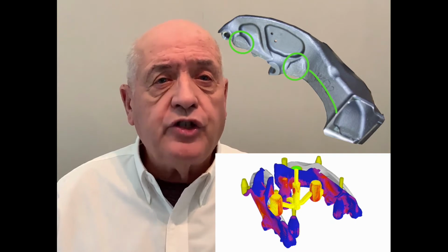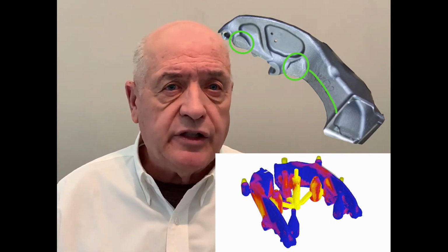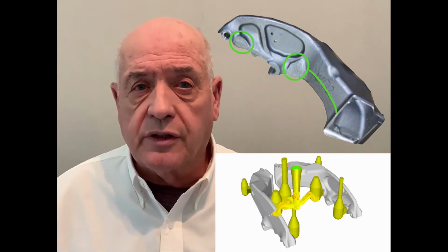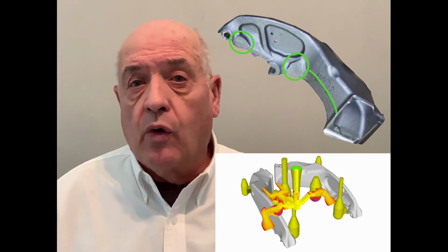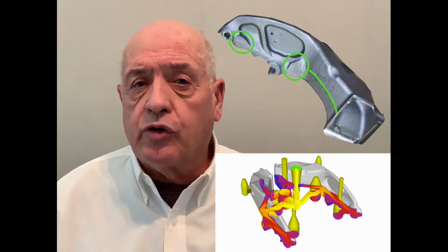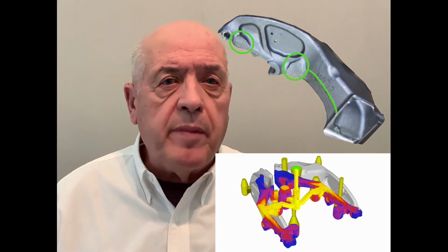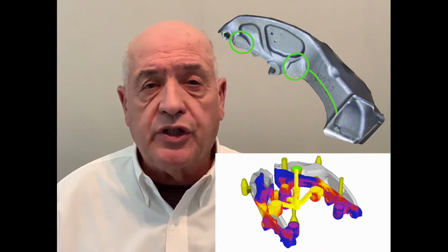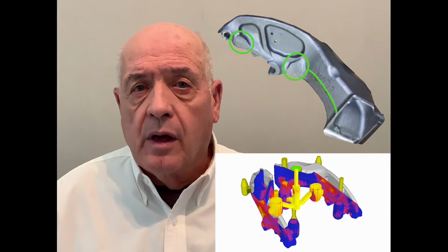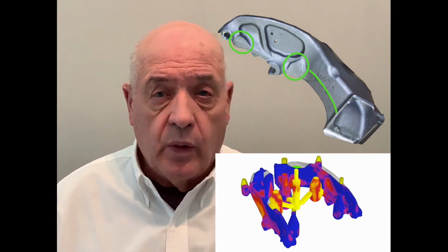So, the first challenge in machining castings is to minimize those variations on the as-cast surfaces that the machining fixture or fixtures will touch. The objective of controlling those fixture target surfaces is to minimize the variation in position and size of the as-cast features that the machine tool's cutting edge will engage.